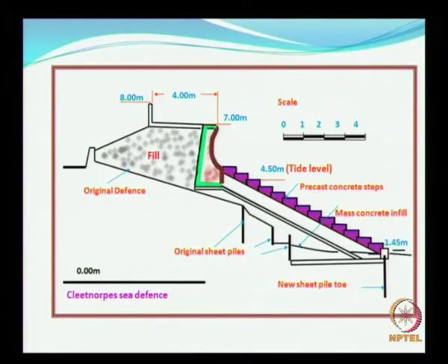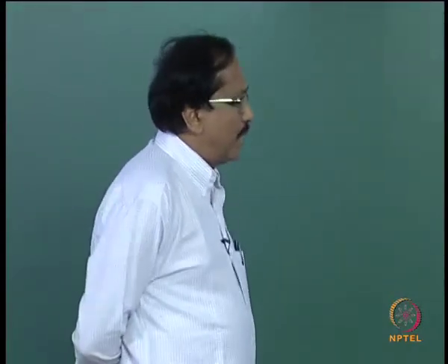With this kind of backing, plus a horizontal distance, even in the event of a coastal hazard, this will take time. In case you have a lot of overtopping, this will be an impermeable surface, and then you have protection provided by a crown wall. These levels are all site specific, and this is quite a good concept, but it is going to be quite expensive.